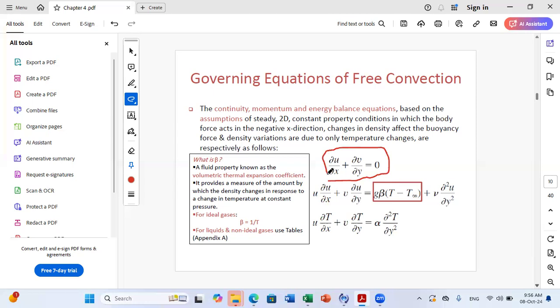While if you apply Newton's law for the fluid, you have the following case. The acceleration of your fluid is related to the forces acting on it. If we observe these terms, this is a force due to temperature difference. So this is the buoyancy force effect, and this is what we call the viscous term, the viscosity forces effect. So here we'll see that in natural convection, the dominant parameter is related to delta T, which is the temperature difference between the surface and the fluid.